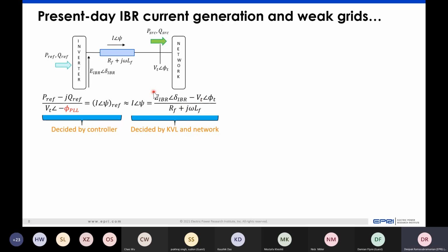So if we do nothing to this AC voltage, which is generated by the converter, and the voltage on the grid side reduces, the current drawn out from the inverter will increase, because that's how Kirchhoff's law works. Just because we have an inverter, we don't abandon Kirchhoff's law on the network. So the current that's drawn out by the inverter will increase if the voltage changes.